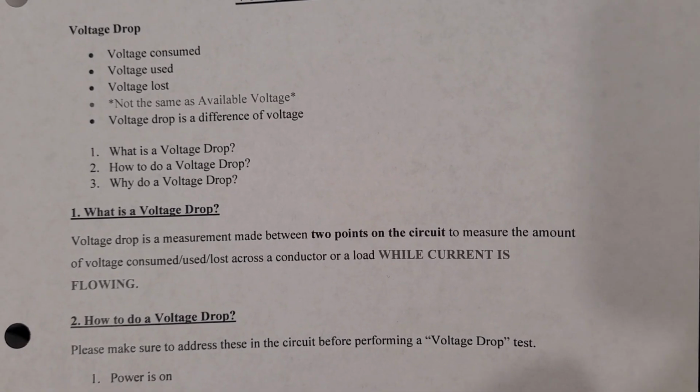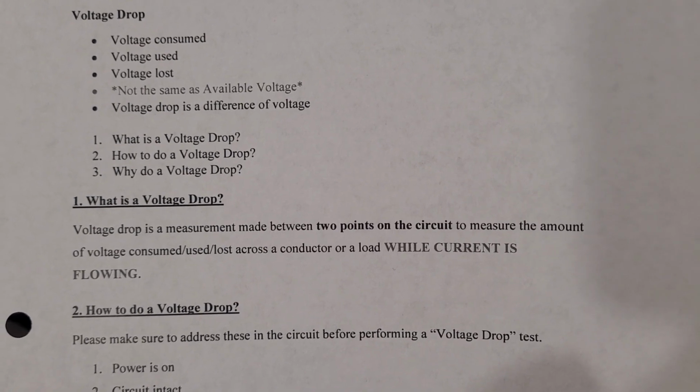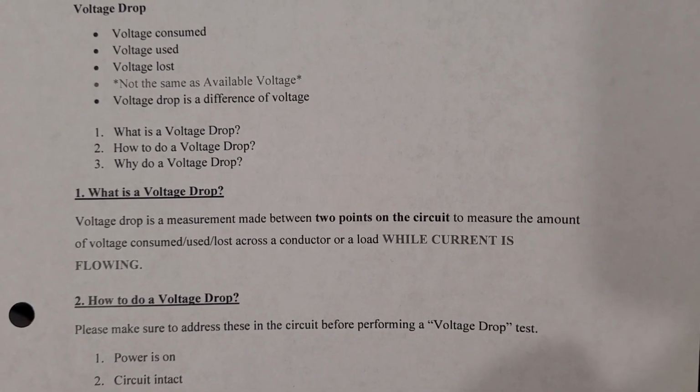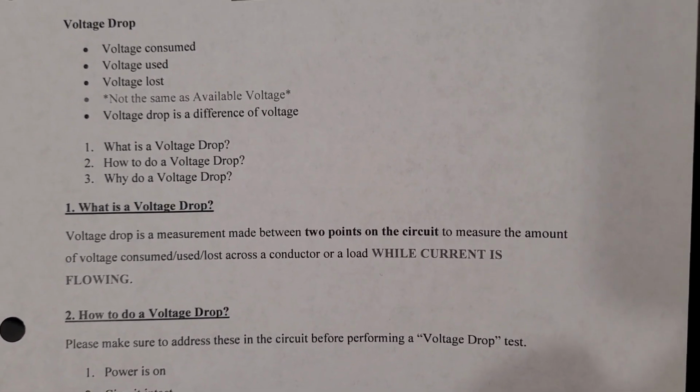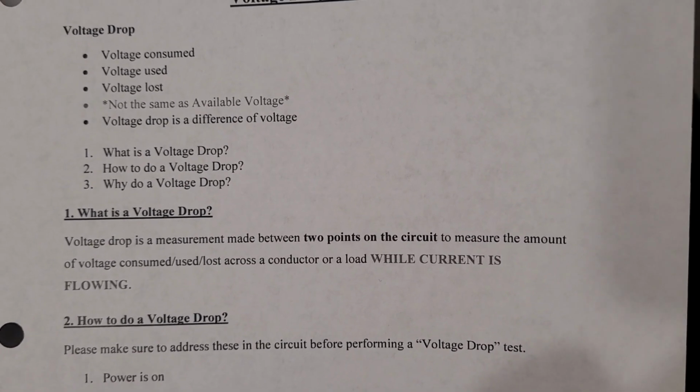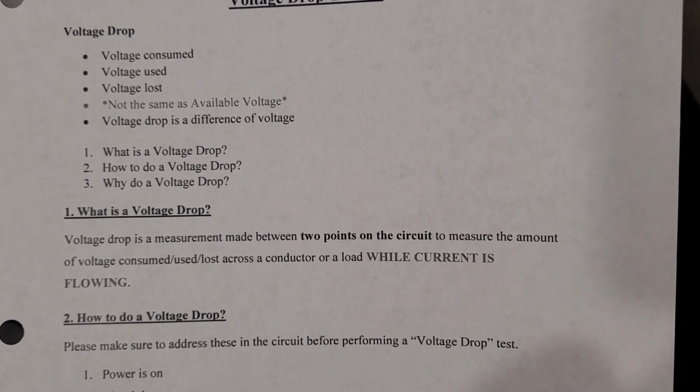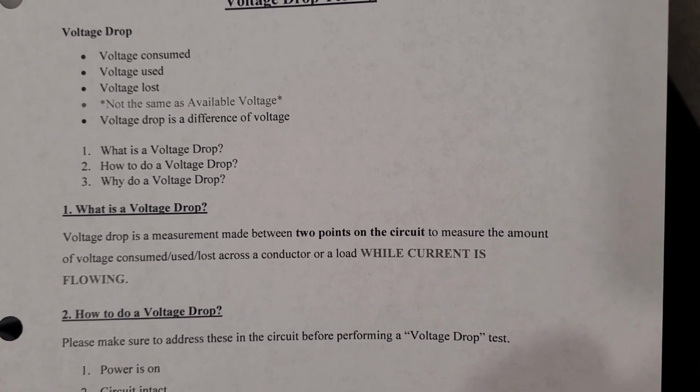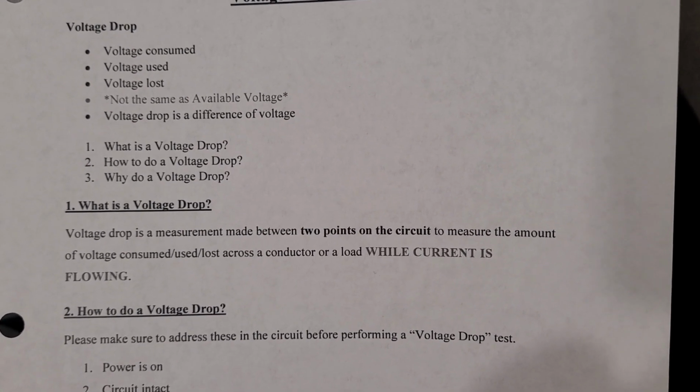Very important here is you got to make sure you do the test while the current is flowing, which is the last thing here in step number 1, in all caps here. Make sure you do it while the current is flowing. Otherwise, there will not be a voltage reading.